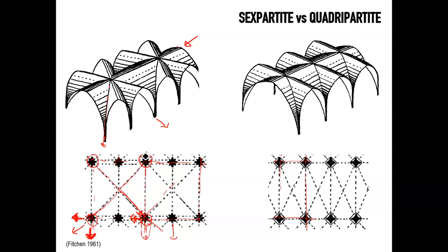And so this is a very interesting reasoning, because if you start to have rectangular bays, this diagonal rib will have a discharge that is bigger in this direction, but smaller in the other direction. You have to be precise when you draw these things, but this component of horizontal stress will be bigger on this axis than on the other axis.